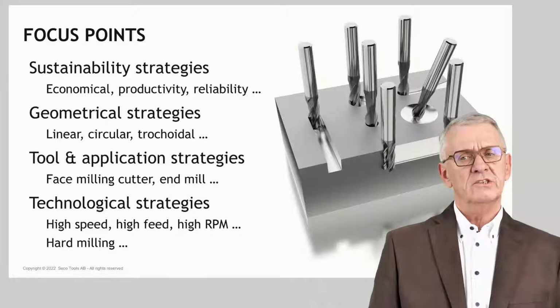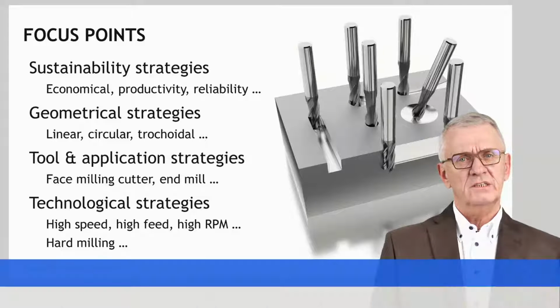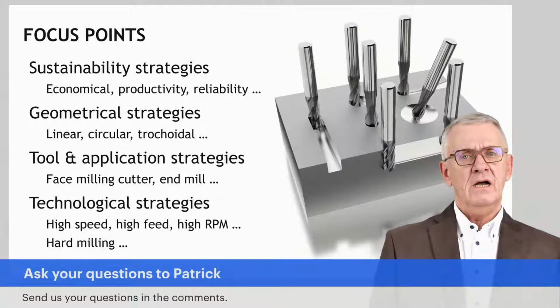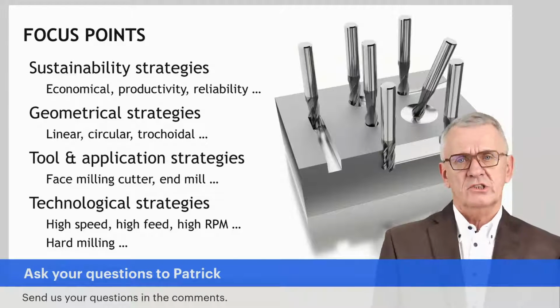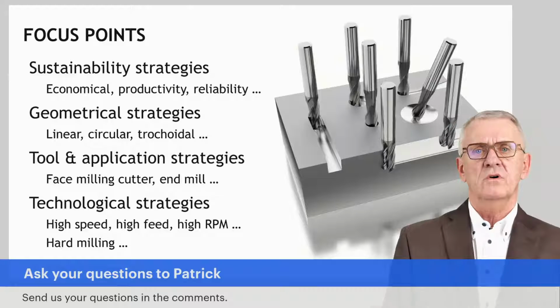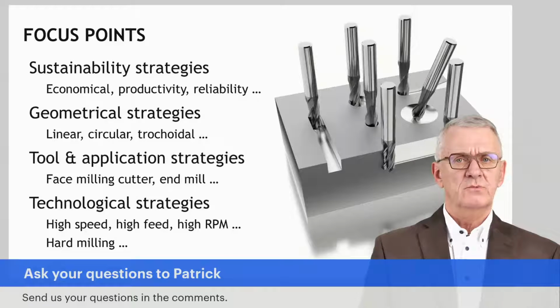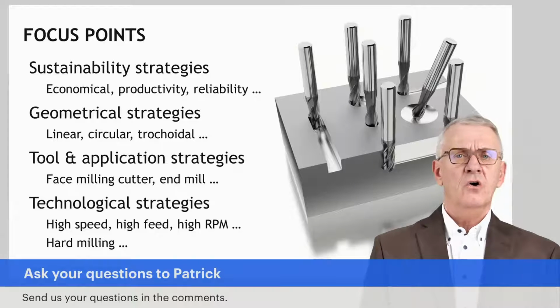Technological strategies is when you look at a cutter with certain features and properties, and at the type of tool part you are thinking of generating, and you make sure that the milling cutter and the tool part can reinforce each other, work together to come to a better result.